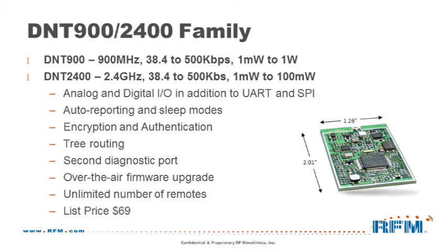they can't. It also has tree routing. So tree routing is a quasi-mesh. It's the same mesh technology that Zigbee uses, as a matter of fact. It's tree routing where there is a hierarchical basis to the network. You have specific routing nodes and leaf nodes, and then a network base or coordinator. But it does allow you to extend the range, and it does it in a more efficient way than, say, a store and forward routing scheme where you have a certain number of nodes that are simply repeating everything they hear. This is really kind of unicast all the way through the network.